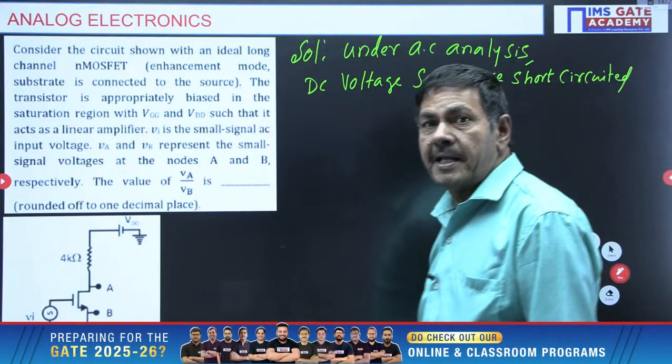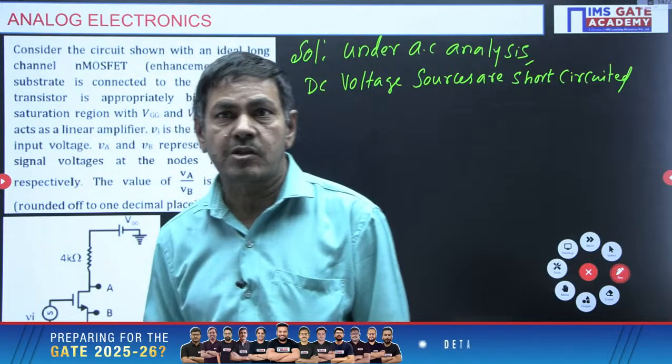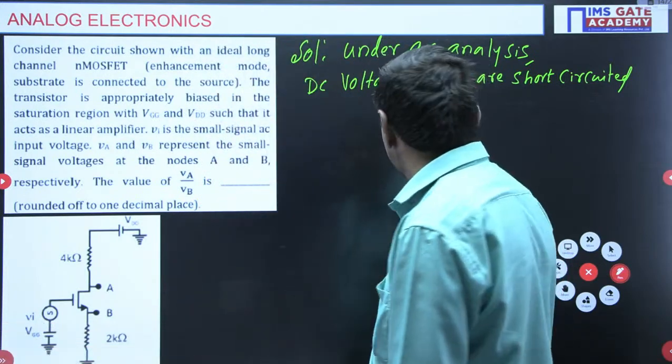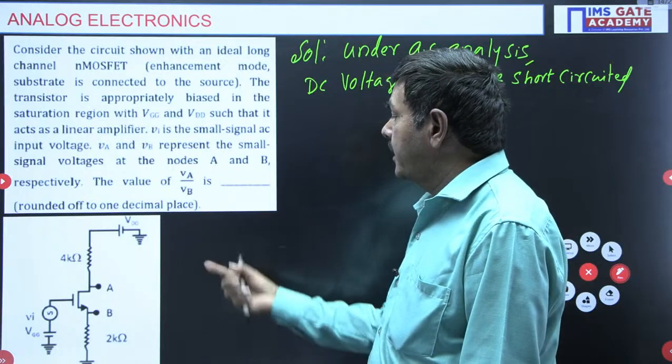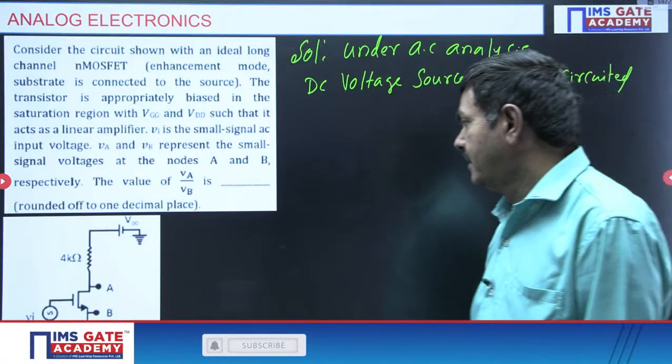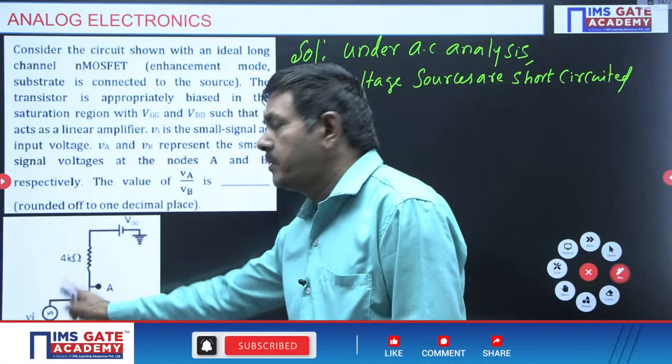If there is any capacitor, under AC analysis you must short it too. But the AC source is to be taken as it is.